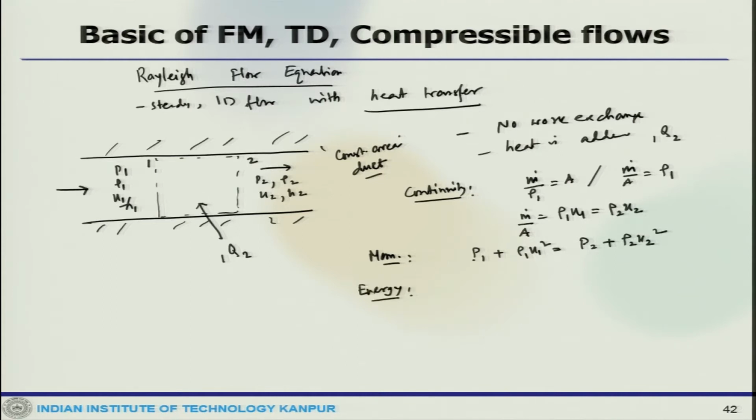The energy equation would be slightly different, that we can see. H2 plus U2 square by 2 equals H1 plus U1 square by 2 plus Q12.